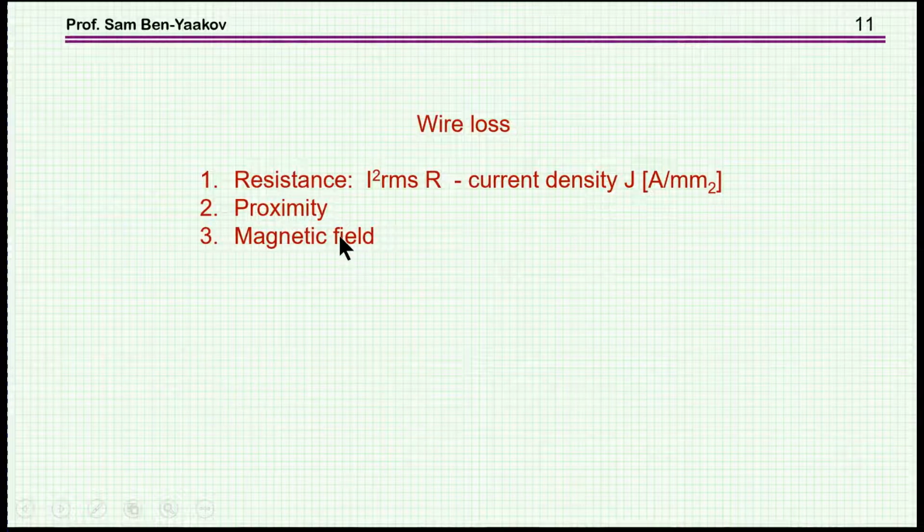There's a packing of wires one beside the other, and therefore the magnetic field created by one is affecting the other one, and then we have a higher AC resistance. Also in magnetics, the same happens if the winding is near a gap. These two are important, but being a primer on the subject, I'm not going to discuss them